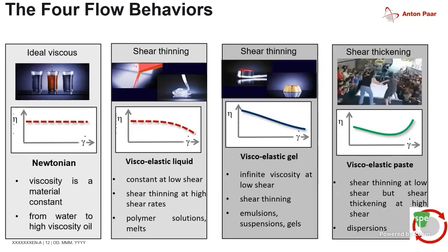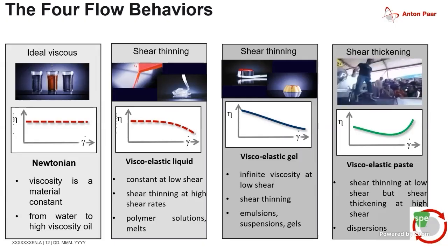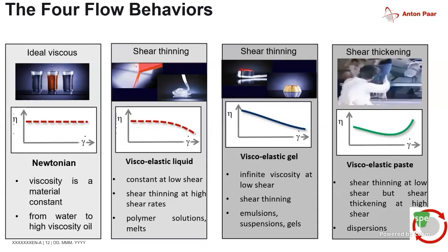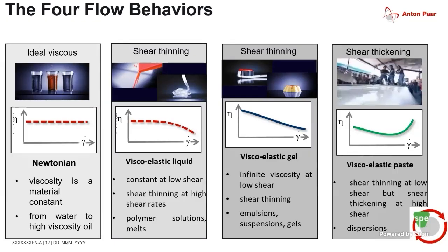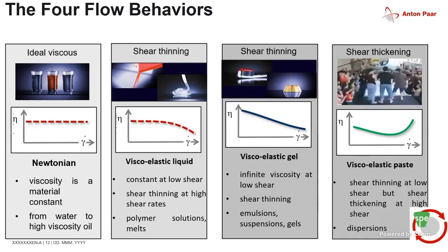Whereas at high shear rates, these particles can't pass each other. So you have this jamming response, and then the material basically hardens up or becomes thicker in this case, which holds those conditions, as you can see by them being able to run across the system. And so these are kind of unnecessary things you don't really want from, say, a processing standpoint, that you have shear thickening, because you don't anticipate a material becoming thicker or more resistant at higher and higher shear rates.